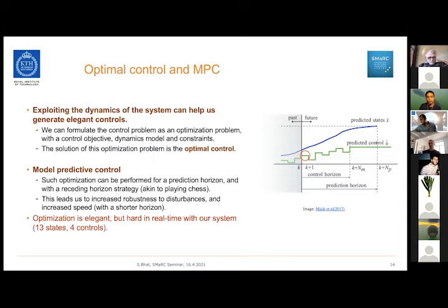So when we do this, we get model predictive control, and you can see that in the figure here. If you have a predicted state, which we propagate the system to, maybe up to a prediction horizon of n, and then if we have certain controls in the green line that is being computed for every time step, we only apply the red circle, and then we again recompute at k plus 1, and then do the same thing again. So this process can continue over and over again in model predictive control.